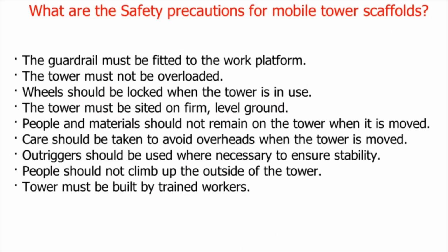The guardrail must be fitted to the work platform. The tower must not be overloaded. Wheels should be locked when the tower is in use. The tower must be sited on firm, level ground.